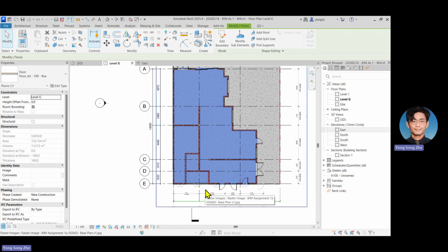Okay, so what is missing currently in this floor? We have two levels of pieces of floor. Is it done? What is missing now for the flooring? Sorry, louder. Toilet. What happened to the toilet? Drop. Very good. So assuming this is the toilet, your toilet might have a different position. Without the drop, if you didn't draw in the drop, the water will flood to your bedroom and then your living room, right?